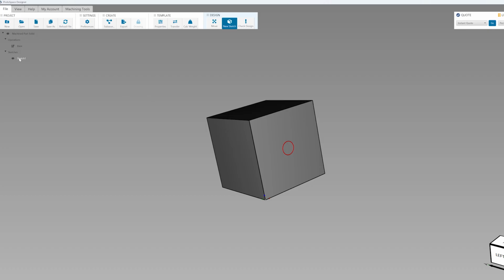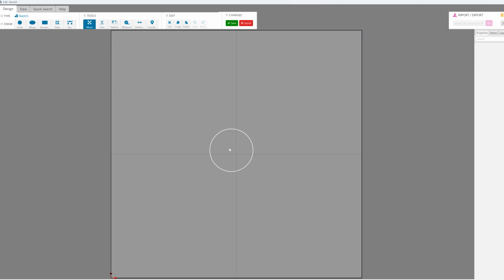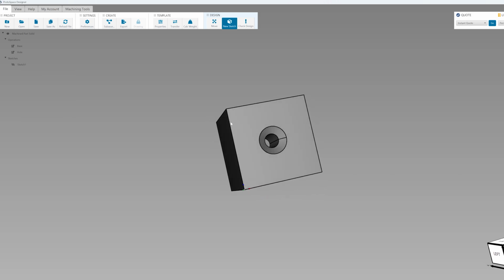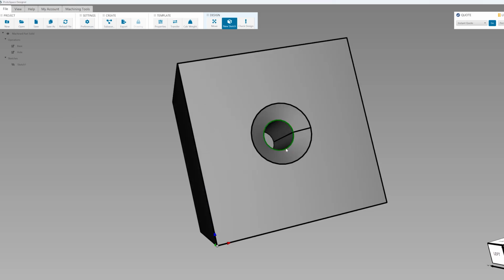Now, to modify a sketch, you use the machining tree on the left to find and edit an existing sketch. You can always select New Sketch too if needed. Now, to apply an operation to a sketch, back in the 3D viewer, right-click it on the machining tree and select the Operations menu and choose the desired action. Think of the operations as building blocks stacked one after the other to shape your final part. If an operation is disabled, it means that your sketch is not compatible with the operation.